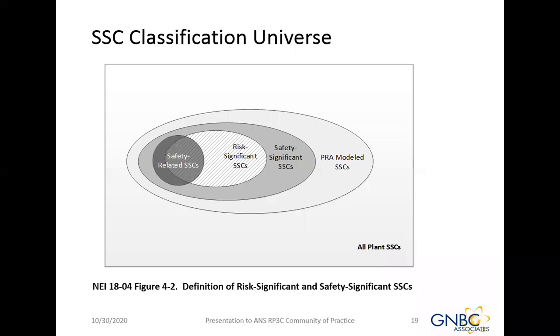There is some subset of the entire plant that's also modeled in SSCs, which are shown here. And part of the defense-in-depth evaluation is also to take a final look at whether or not there are any other hazards in that remainder of plant SSCs that might have some bearing on the safety case. So this is a complete representation of all the things that get captured within the LMP scope, but the defense in depth evaluation doesn't lock itself in to just the PRA model SSCs. It looks at the whole plant.